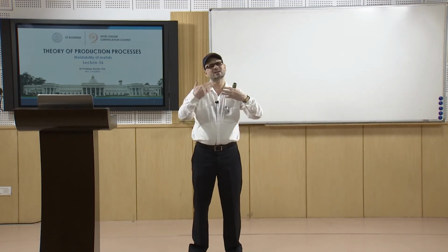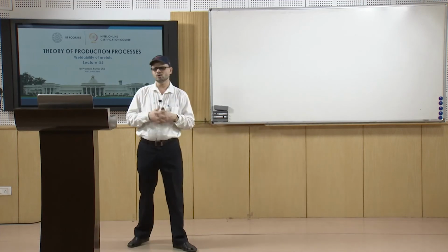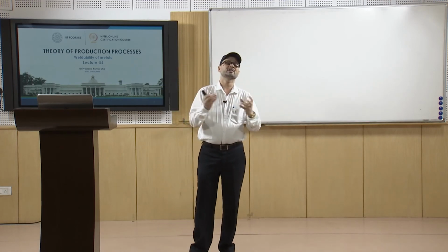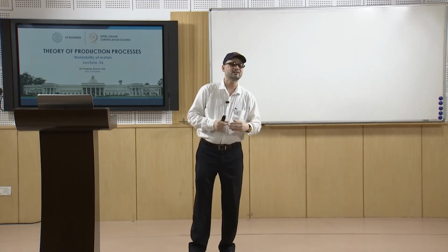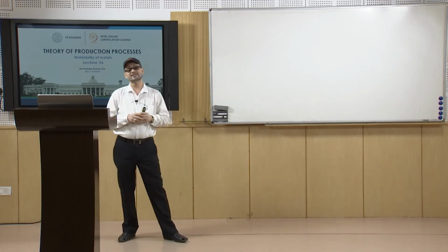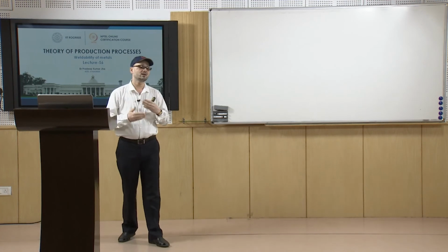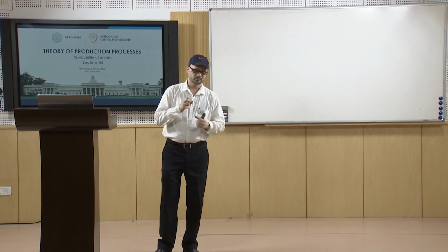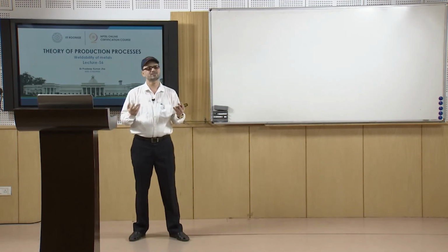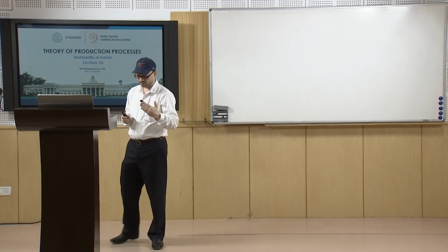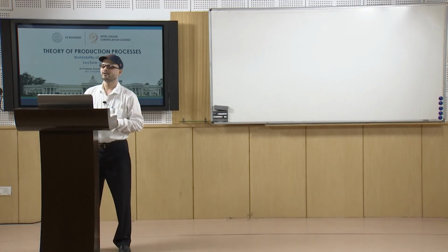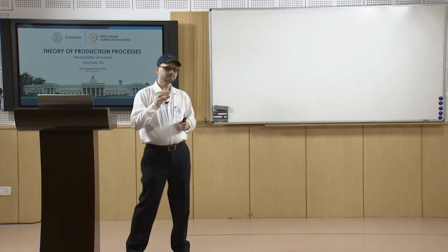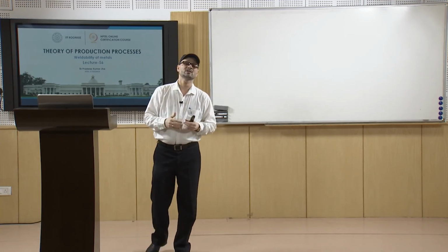But then you will have to know what the proper process is by which even these materials can be welded. You may go for some kind of solid state welding, where you do not give the time even to fuse them. You are joining by other solid state welding processes because of the friction which is generated, like friction stir welding. So, what we mean to say is that in this case we try to have the appropriate welding process selection. Similarly, there may be information about the preheat.